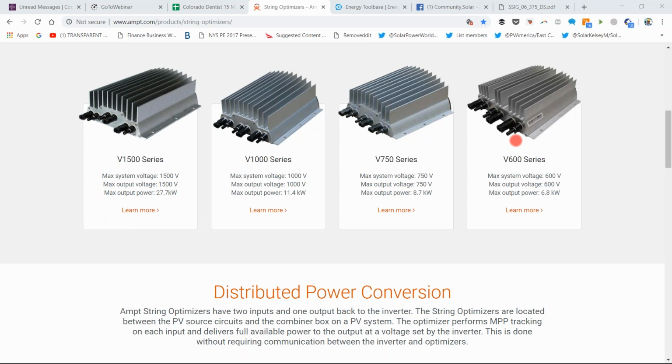So for the most part, unless the array is turning off completely from cloud coverage passing through, they fix the output voltage from the array and vary the amperage rather than the other way around. And so what we see here are voltage regulators for commercial and industrial systems that can supply a fixed voltage output starting at 600 volts, but going all the way up to 1500 volts.